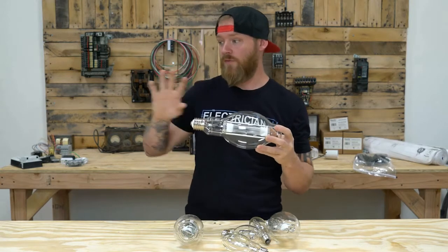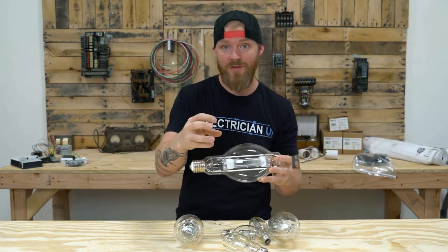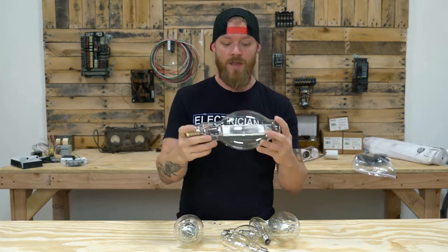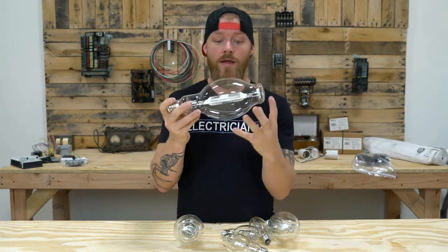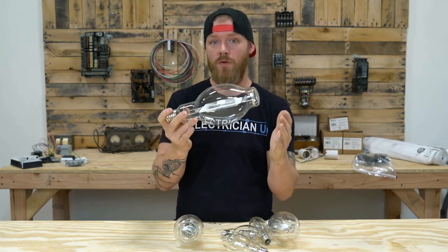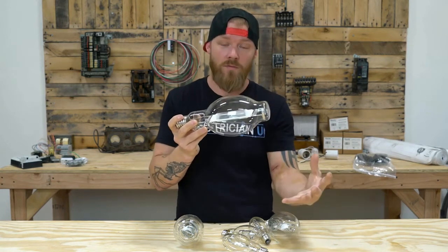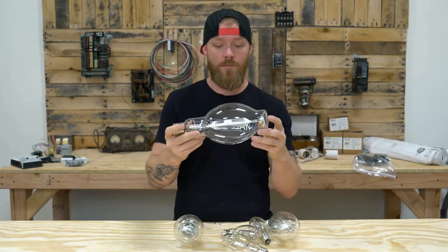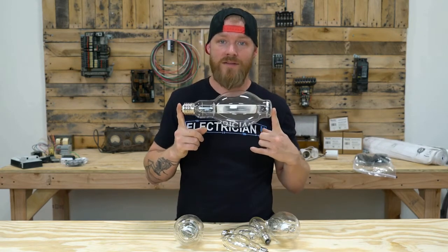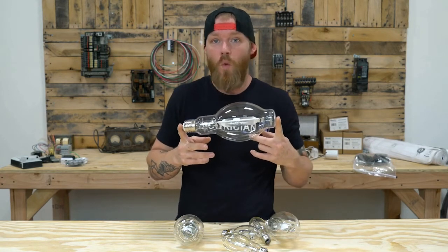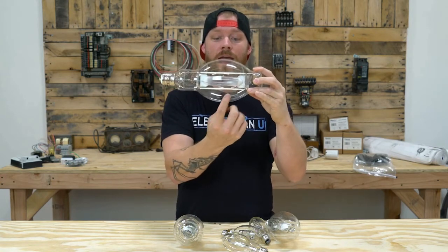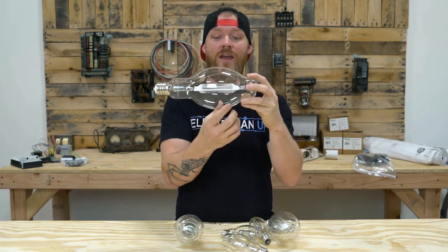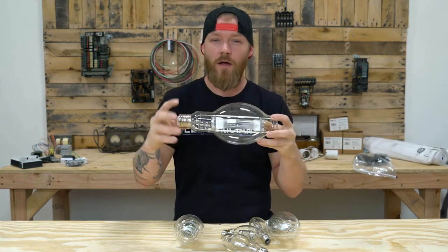So instead of a fluorescent lamp relying on phosphorus to get its luminescence, the arc alone inside of here is bright enough to strike a light, but they want to control the color output so that it produces a certain amount of light and a certain spectrum of light, really. So these burn at about 4000 K, which is a pretty white color. But those halide salts on the inside of this each have their own color profile.